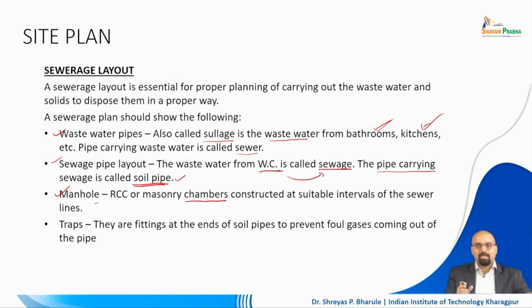Manholes also have a cleaning grate or cleaning mesh, from which additional waste that is not to be drained in that sewage pipe or waste pipe can be collected separately, right. These are placed at intermittent intervals based on the distance of the sewer line and of the wastewater line going towards the sewer, right.